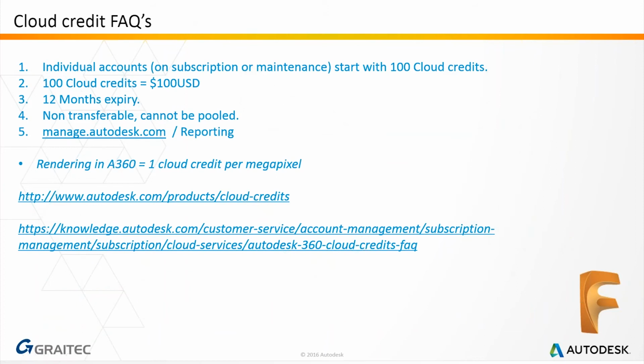Okay, so once I've told Fusion which elements I'd like to preserve, I then need to add some loads. So I'll come up here to loads, and I'm going to add a structural load on the end here, and that's going to be 500 newtons. So I'll say OK to that. Okay, so now I have a load and I have some preserve regions.